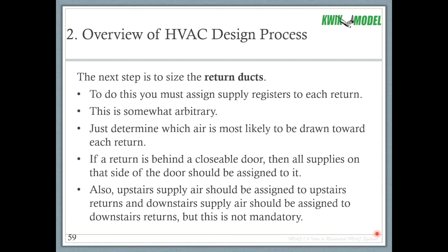Now the next step is to size the return ducts. To do this, you must assign supply registers to each return. So what you do is you determine where the air from each supply register is going to go. You'll say the air from these supply registers over here are all going to go back to this return, and the air from these supply registers over here are going to go to this other return. So it just depends on where the supply registers are in relation to the returns. If there's only one return in the house, that's easy, they're all going back.